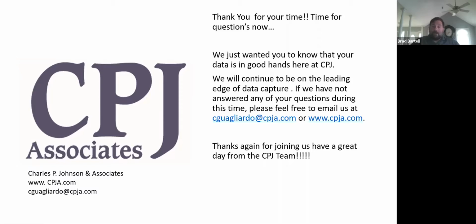But you want to be careful of your surroundings too. That brings up another point. When you're operating a drone, you want good conditions. You're not going to operate a drone in the rain or the snow, or in a heavy wind. You primarily want the wind to be under about 8 miles an hour on the ground, because the higher you go up, the more the drafts come.